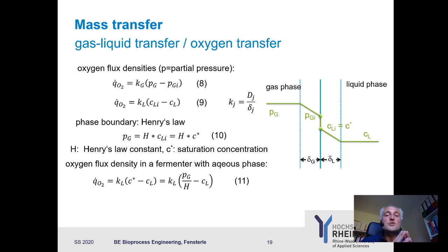So this means if you want to calculate the overall rate of the transfer from the gas phase to the liquid phase, it's enough just to look at the rate of the gas transfer here in the liquid phase, because this is not even a percent difference in this case. And this is, of course, not relevant for such a system. So this means that for this transfer, we only need to look at this gas transfer here. And this is then at the end the equation we come up with.